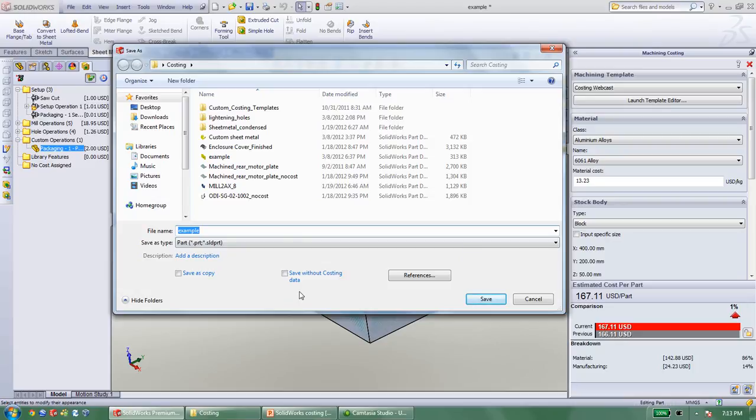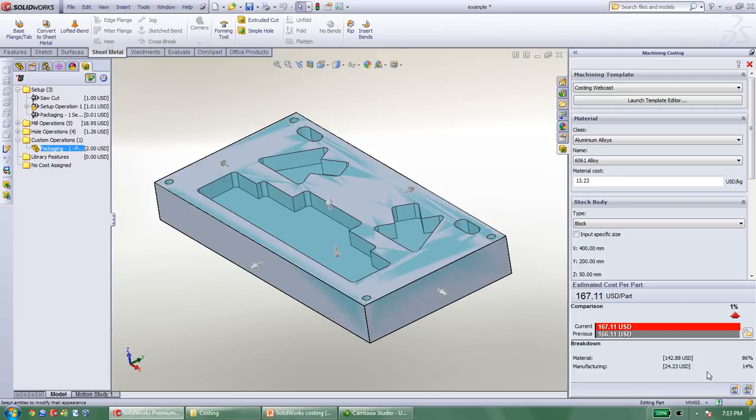Some other things I've run into, I've mentioned that the templates are read-only, at least the default ones. You cannot run this report command with Word open. So be aware of that. If you have Word open, you don't want to hit the generate report command. It just won't work. You'll get an error.